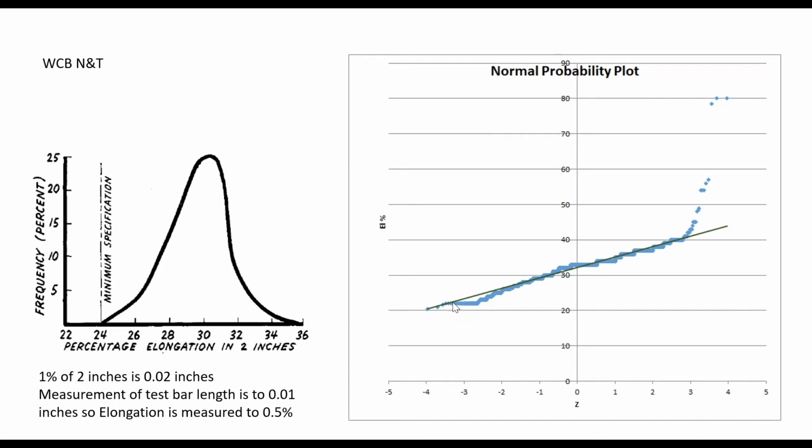So I want to make a really good measurement to make sure I don't mess up the measurement and say that the material doesn't meet the qualification. So even if I am spectacularly honest and really critical in terms of making the measurement, I am going to frequently find that with a remeasurement, if I'm careful, that measurement will put me back into compliance. So I have an incentive and a real bias towards measuring things so that they're in compliance with the specification.